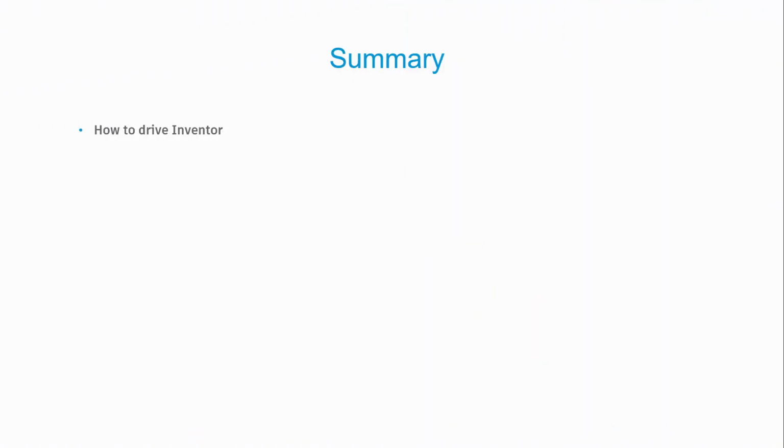What we have seen today. We can drive Inventor using iLogic scripts. It can be delivered to Design Automation in 3 different ways. URL inside the parameter, which you have to provide before every work item. URL inside the settings, where you don't have to provide the link every time, but it's still downloaded during work item processing. And inside the app bundle, the way when you want to leverage Design Automation binary storage and app bundle's versioning capabilities.